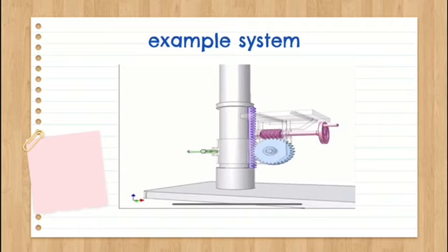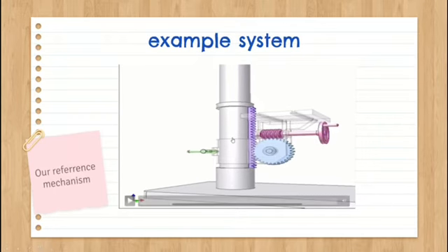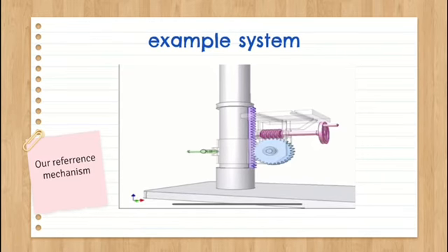This is our example system that we use for our table adjuster. Our table consists of a shaft which has a worm attached to it, and also a gear and the pinion which is attached to the rod of the table. The user will rotate the hand crank, where the rotation will transfer through the shaft, and at the end of the shaft is the worm, which will transfer the rotation to the gear. The rotation from the worm will determine whether to increase or decrease the table.